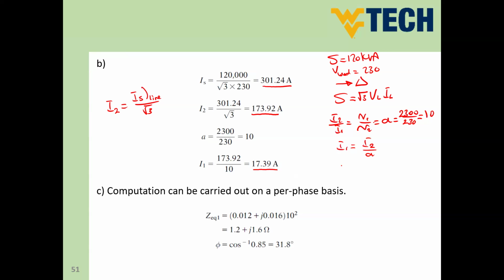Remember that our connection is Y delta, and this is the primary winding current, the phase current. For Y connection, you know that the phase current equals the line current. So this is going to represent the ideal transformer primary current. So this would be now the value of the phase and line current of the primary winding.